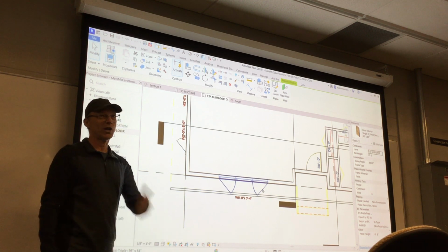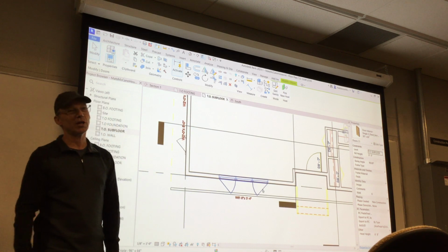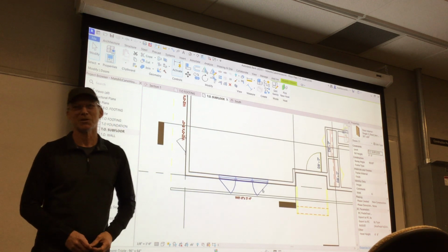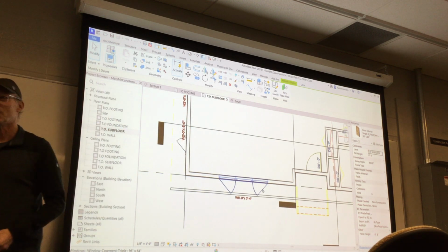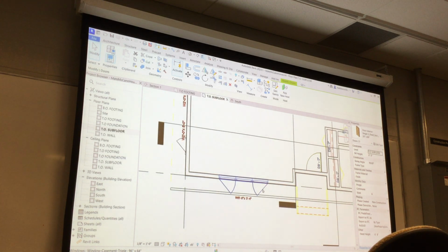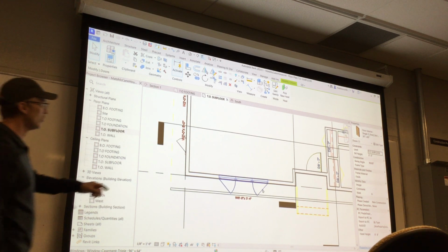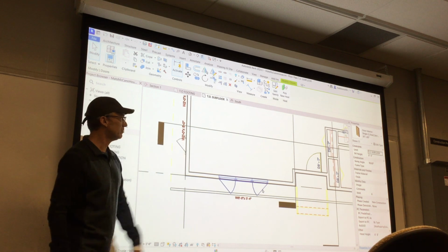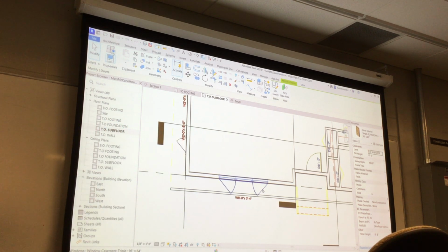Somebody had one of those swinging into the house. Do casement windows swing into the house? No, never. The pressure, they would leak, right? Remember building science? If you have a casement window that cranks out like that, it has to open to the exterior, okay? So I know you're in a hurry or whatever. Casements are usually, yeah, I don't know, not much bigger than 2 feet wide, any one I've ever seen.